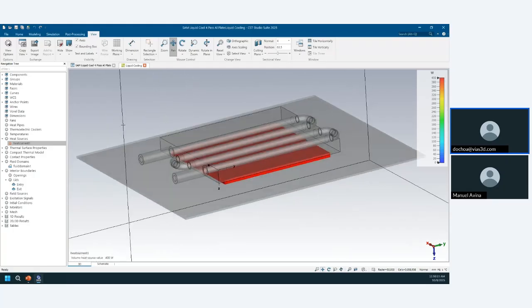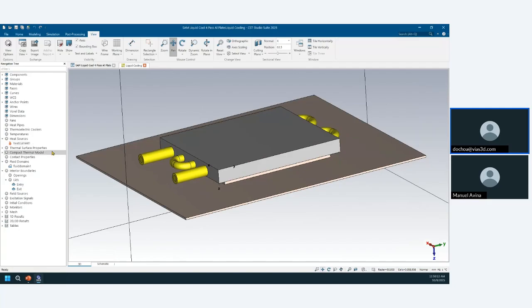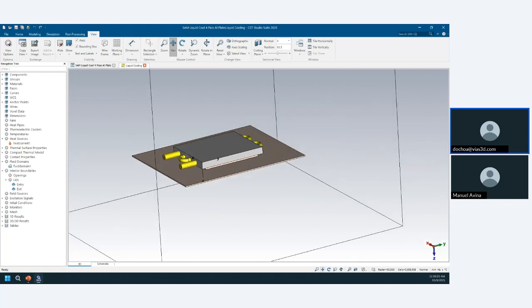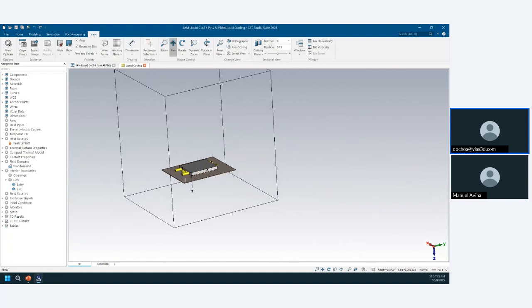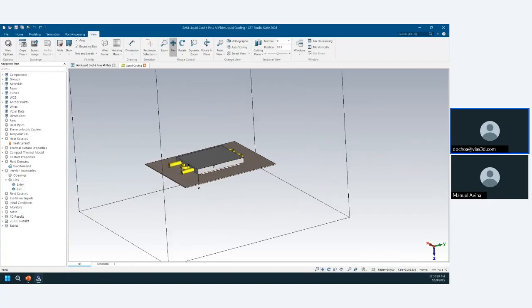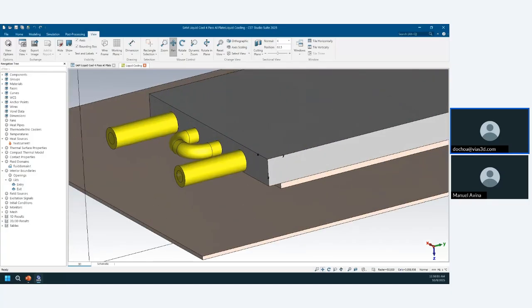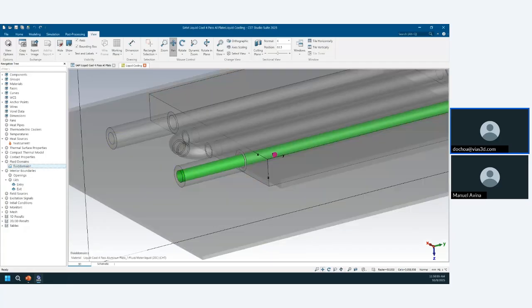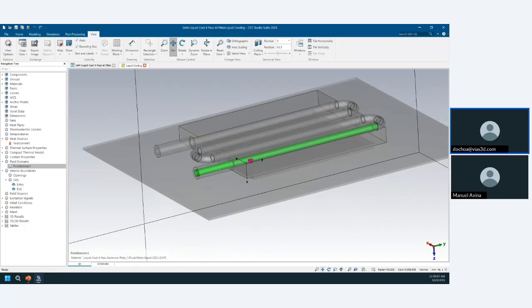And the way you go about creating that fluid, first it has to be enclosed. You have to be in a model completely closed and separate from the background. As you see, the fluid is going in here, the background is surrounding that fluid. So we have to separate that either with a solid or with a lid. In this case, I use a lid. So let me show you my fluid domain. It looks something like this.